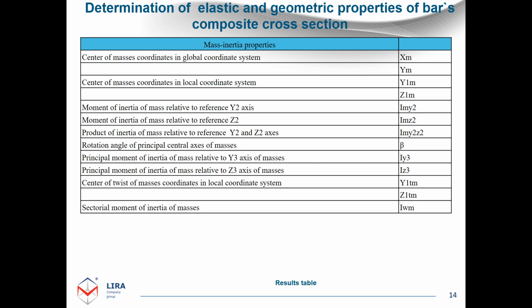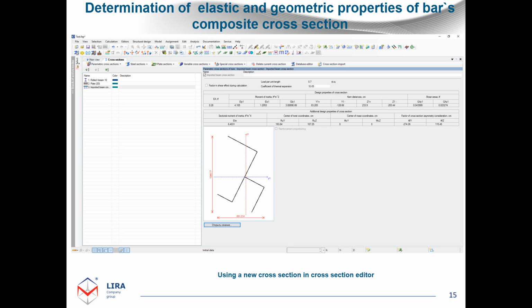After the calculation is complete, you can use a saved file to add cross-section to the cross-section library for the strength analysis. So while adding cross-section, you can specify the file in which this cross-section was created and calculated. Program will automatically display this cross-section and show all main stiffness properties obtained for it. Then it can be assigned to bar elements and you can perform a strength analysis.